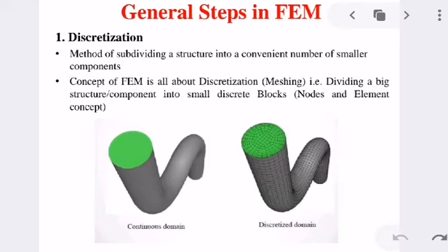Mesh generation as a pre-processing step to FEM involves discretization of solid model into a set of points called nodes, on which numerical solution is to be based. This I already mentioned. So finite elements are then formed by combining the nodes in a predetermined topology, such as linear, triangular, quadrilateral, etc.